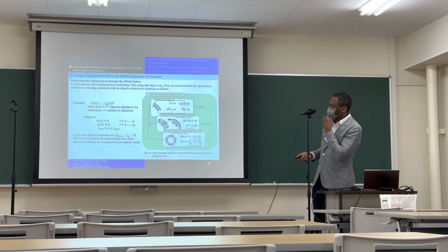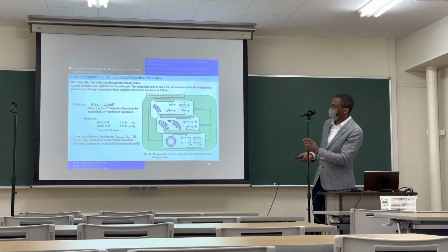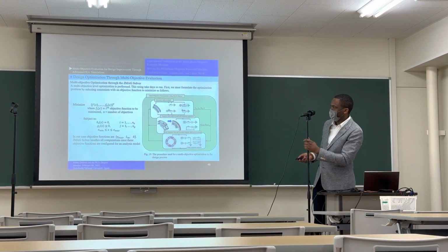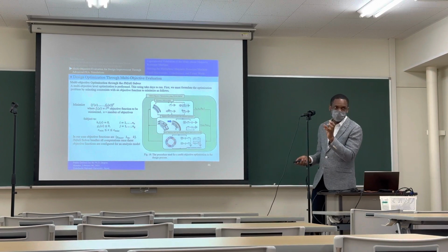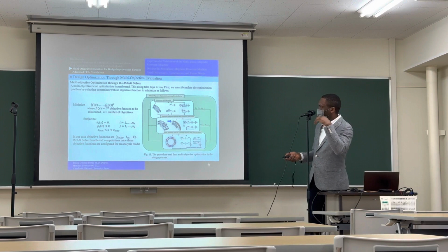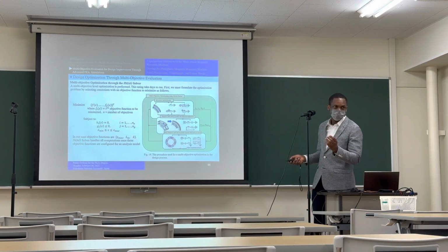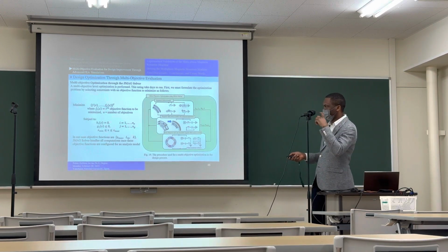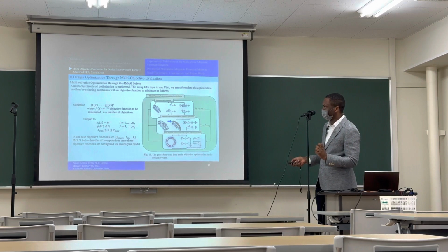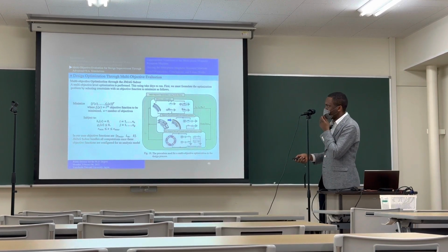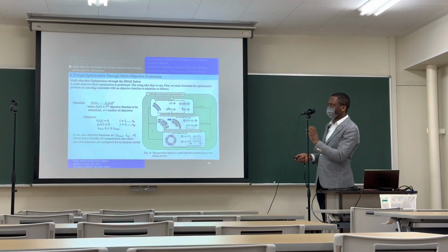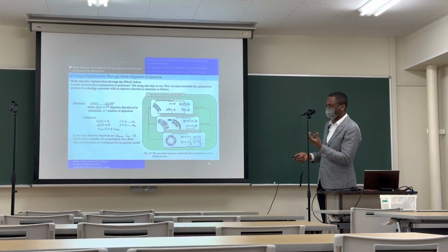So we'll design different shapes of this. We'll draw one of these models, and then the machine can calculate for different shapes and different sizes of wire. Let's say we'll leave it to run overnight to determine the best size of the machine and the best shape of the machine. The process will be repeated inside the JMAG software many times, and we can get an optimal design. So we use this kind of procedure to get the best design of the machine.